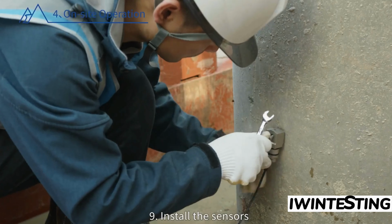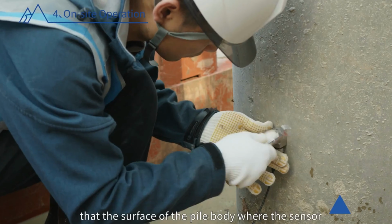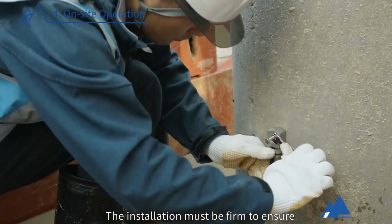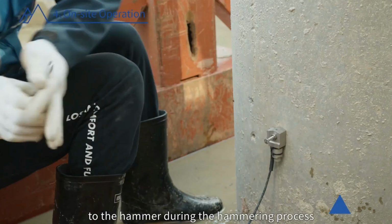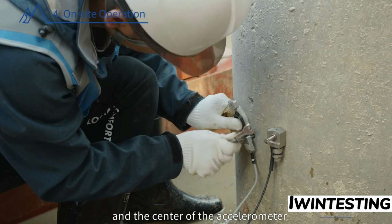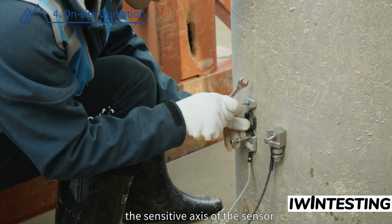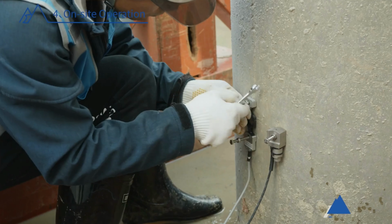9. Install the sensors. When installing, it should be noted that the surface of the pile body where the sensor is installed should be flat. The installation must be firm to ensure that the sensor does not slide relative to the hammer during the hammering process. The center of the strain transducer and the center of the accelerometer should be on the same horizontal line. The sensitive axis of the sensor should be parallel to the central axis of the pile.